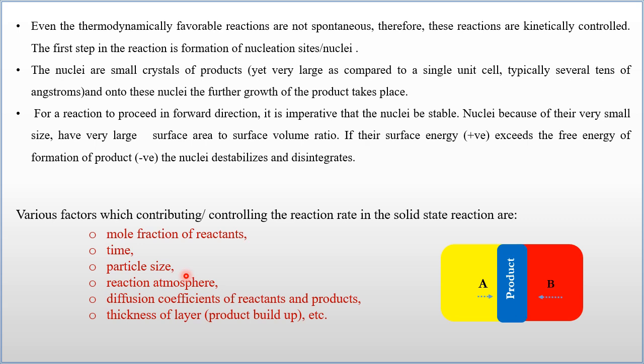Or the product may take a few oxygen as oxide ions, and they will settle in the interstitial sites and change the stoichiometry of the product, or may create some defects in your final product. So that is why sometimes it is very important to control the reaction atmosphere.